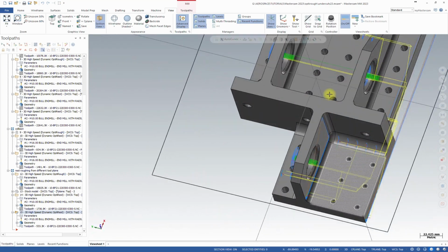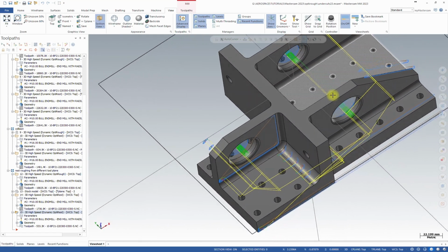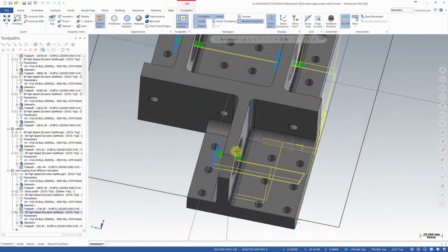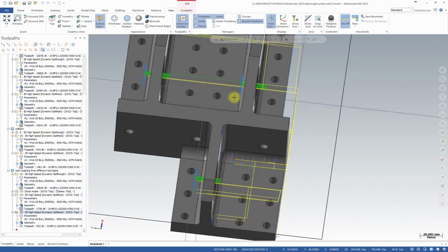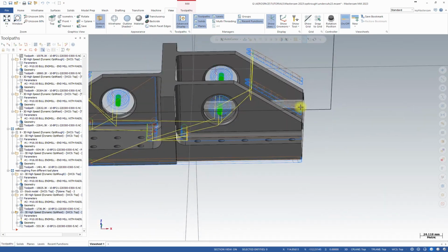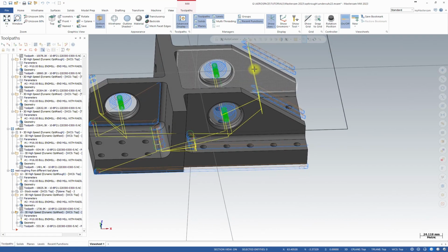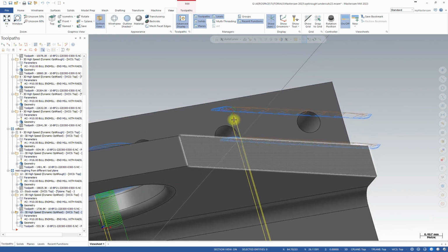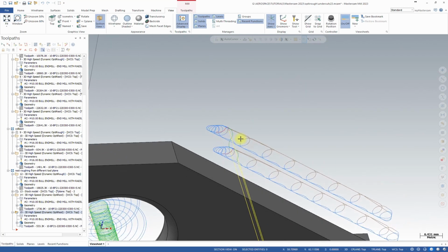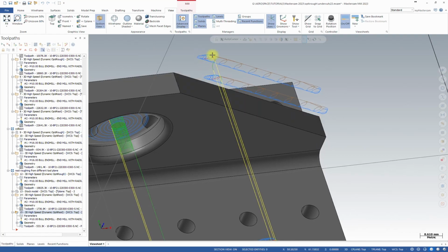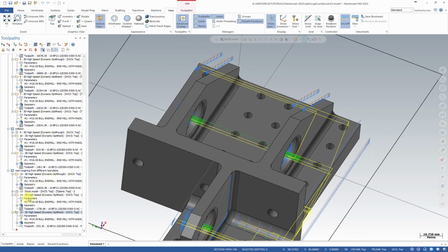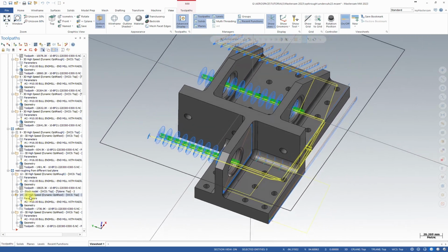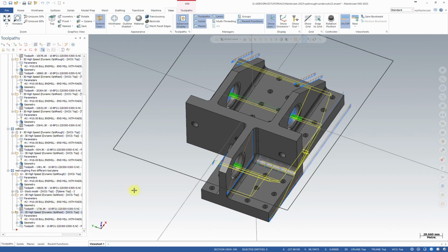Basically, this is the efficient roughing, because we only rough places where the material is, where the stock is to be machined. Okay, so look at that, 2 depth cuts here, 2 depth cuts on the walls, and the passes are produced only where the material is. Look at that, nicely done, that's awesome. Okay, so this is the improvement I will use a lot. Look at the difference, this is completely different toolpath. Look at how much wasted motion we had in comparison to this one.